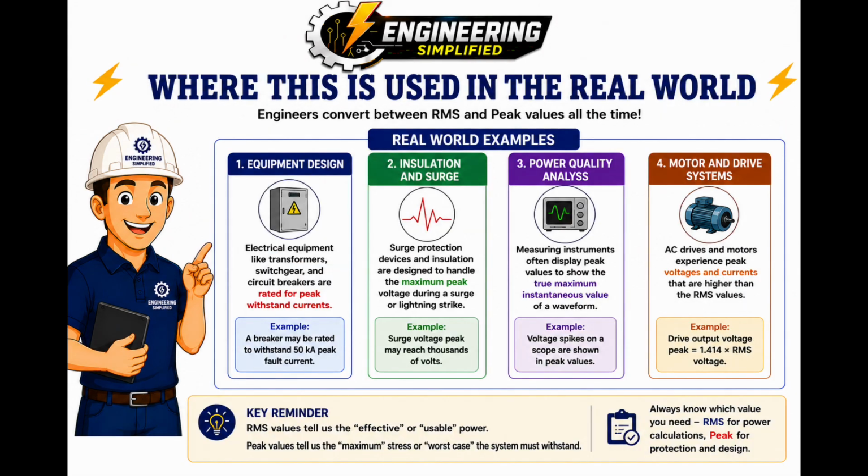This simple conversion appears throughout electrical engineering. Engineers may need RMS values when considering power and equipment ratings, while peak values may be required when assessing insulation, surge conditions, semiconductor stresses, or maximum electrodynamic forces. The important thing is to understand which value the calculation or equipment specification requires.